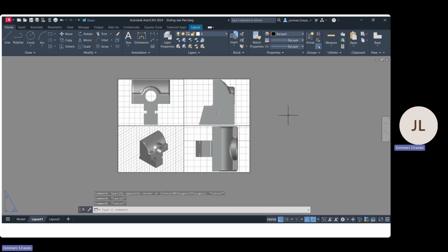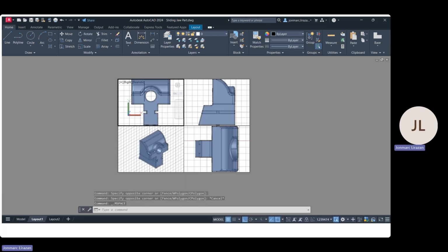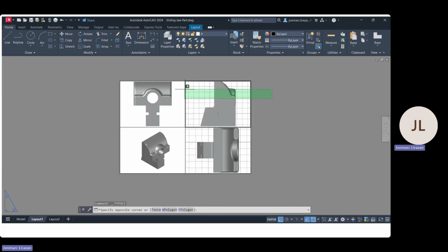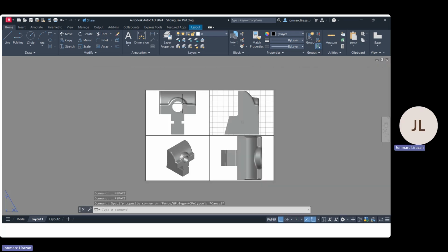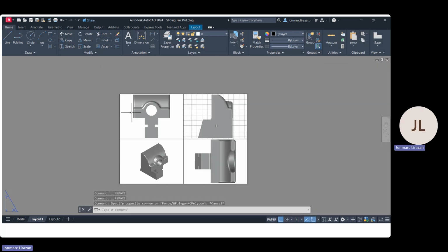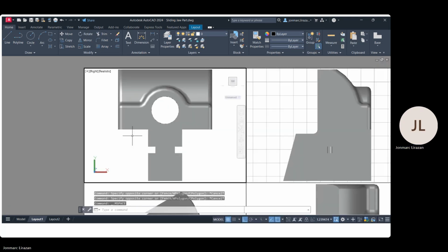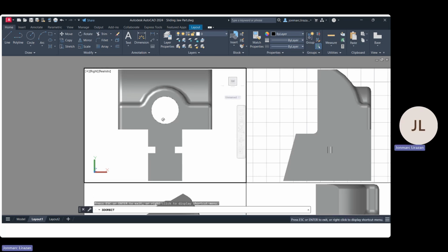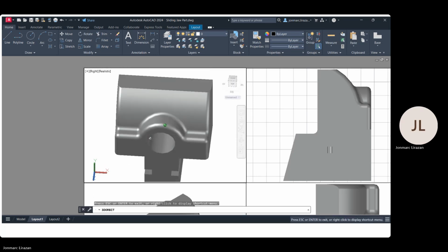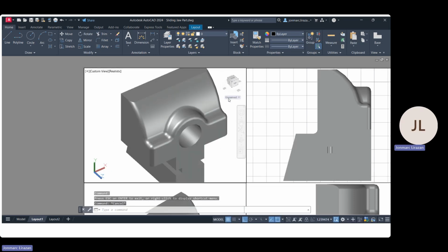Okay, so click the outside. Again, please remember that this is the outside area and this is the inside area. When I double click this area, my cursor will be transferred to the drawing area. Again, when you click the outside area, you can zoom the paper. You can zoom in and zoom out. You can adjust everything outside. But if I double click this one, my cursor will be transferred and I can edit the view, or whichever view I wish to. So just make sure of this one.